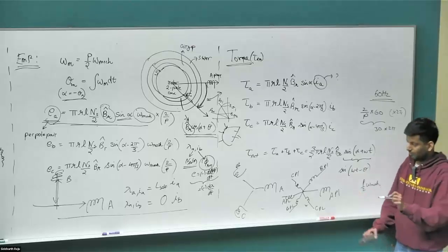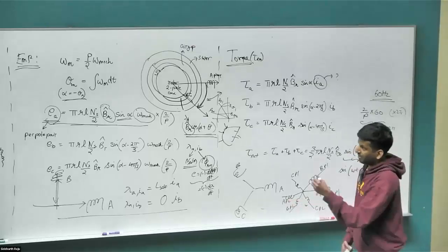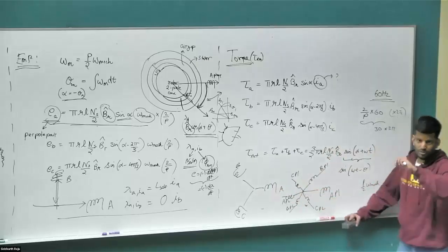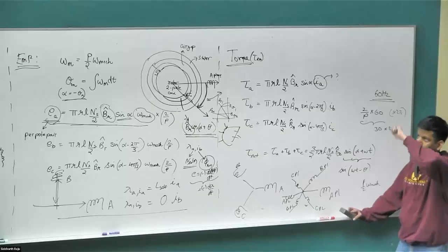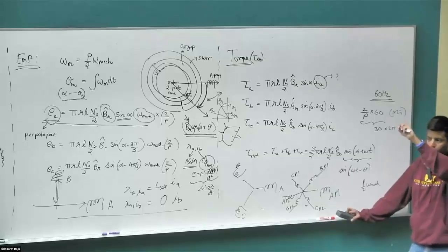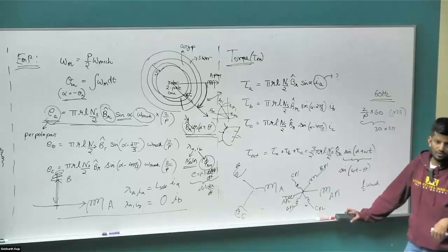Right? So these are completely different things. Just for simplicity, I'm drawing this diagram, but when you have higher poles, this is effectively what it looks like, because if you remember, the winding went from positive to negative within one half of the motor for a 4-pole, and then negative to positive. That is the other set of winding. You have the option of connecting the top set and the bottom set in parallel or in series.